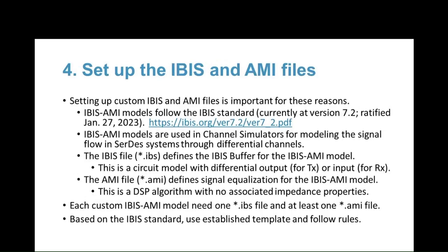And now we want to set up the IBIS and AMI files. This is important for many reasons. The models follow the IBIS standard currently at version 7.2. It was ratified just last month, not too long ago, January 27th, 2023. And IBIS-AMI models are used in channel simulators for modeling the signal flow in a SerDes system through differential channels.